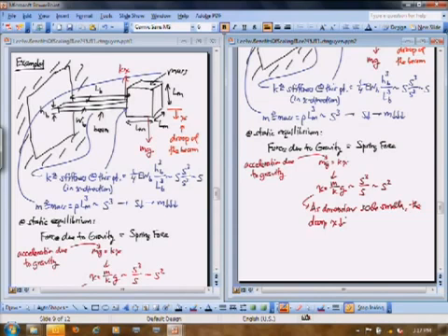And so what we're particularly interested in is our thermal resistance. So let's go back to our thermal resistance. How does this impact thermal resistance? Well, thermal resistance, remember, goes as the length divided by the width divided by the thickness, and we want to raise this thermal resistance. So it's interesting to figure out what happens if I maintain constant droop. Say I had a droop in the beginning at a certain dimension, and then I scale everything down, but also increase the length, increasing the thermal resistance while scaling such that I maintain that droop. What happens to that thermal resistance?